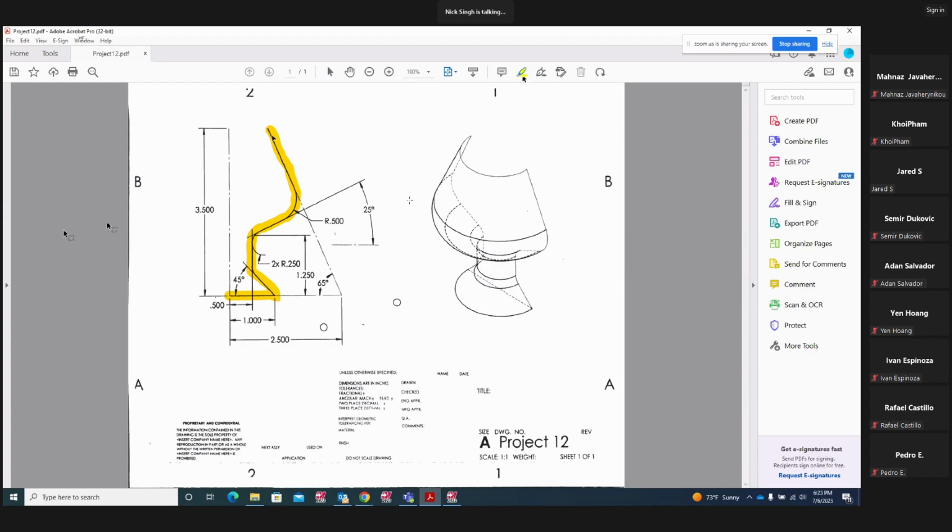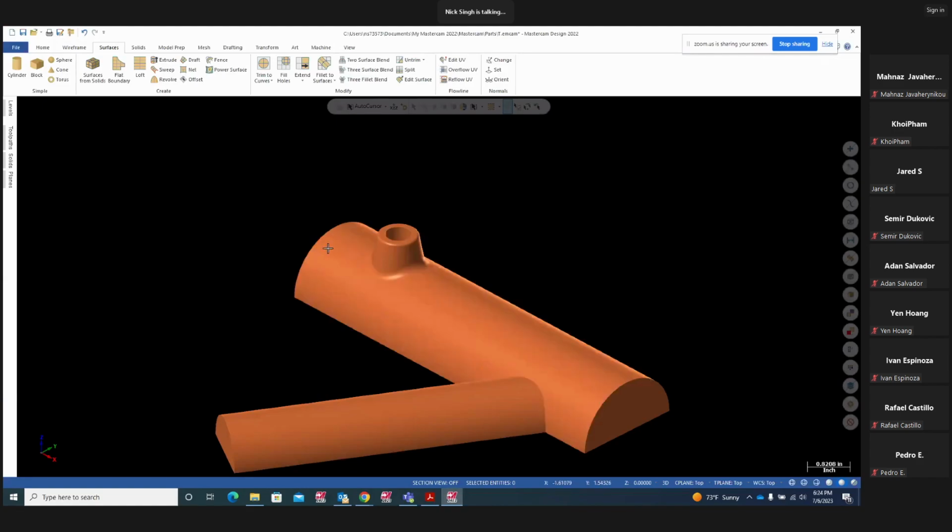So I'll go ahead and create this geometry on a top plane, and this 3.5 inch line right here is not a part of the geometry. This is going to be my axis of rotation, so I'm going to use a revolved surface on this. This is my geometry right here, the one you see in yellow. So I'll go ahead and go with construction plane top.